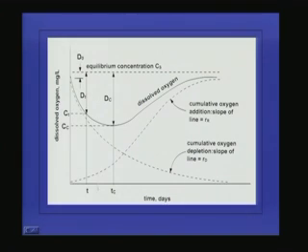So the critical time or critical deficit will not occur immediately after the waste discharge. It will take some time for the critical deficit to occur. So we can find out the critical time or the distance at which the critical deficit will occur, and this information can be used for the management of effluent discharge. So this is the use of this dissolved oxygen model.